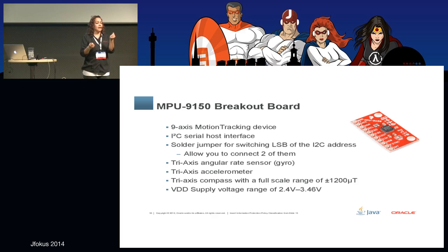This is when I need the reading from the accelerometer to find out if the device is flat or not. Because if the device is still with a slope, I should keep doing something because it's supposed to keep moving, okay? So that's why I actually need a combination of both. The gyroscope will just give me the rotation information, how fast you rotate, okay? And the accelerometer will tell me, okay, are you still tilting or you're flat? If you're flat, stop any movement. If you're tilting, do something. So that's why I actually needed both readings.